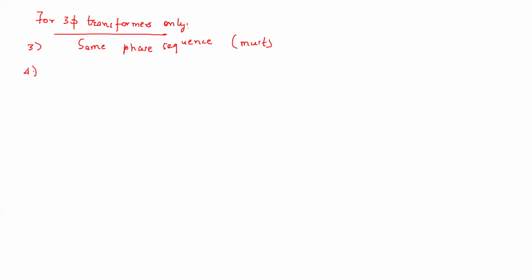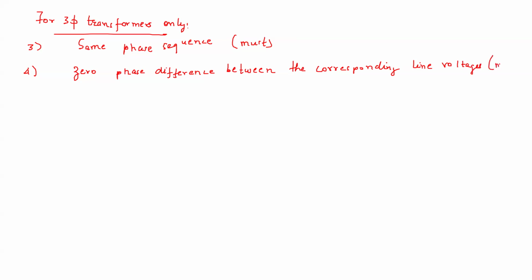And the second is zero phase difference between the corresponding line voltages. Okay, this is a must condition.